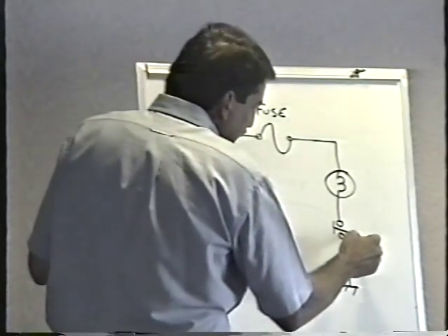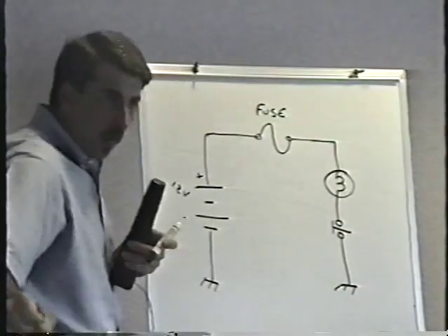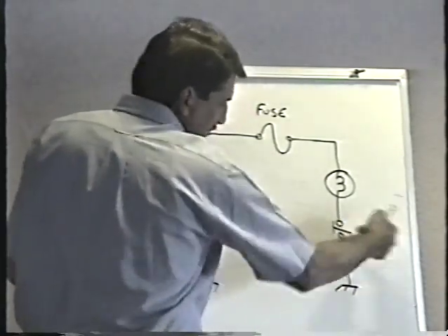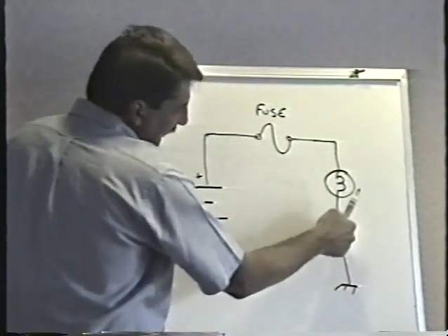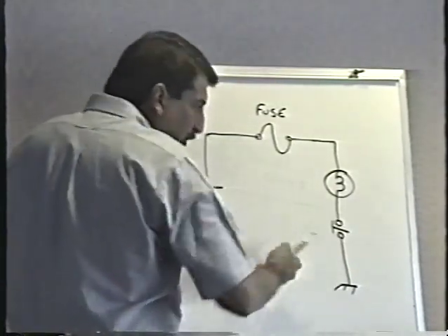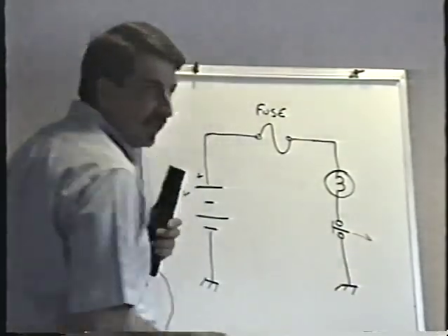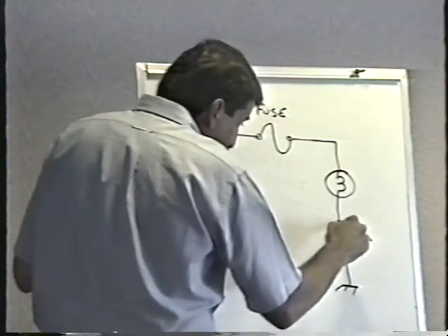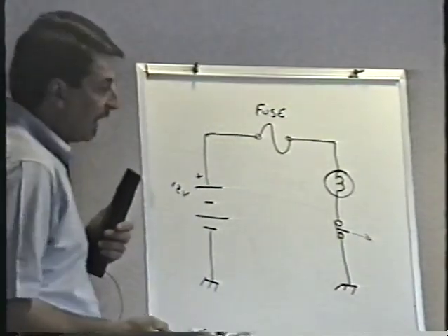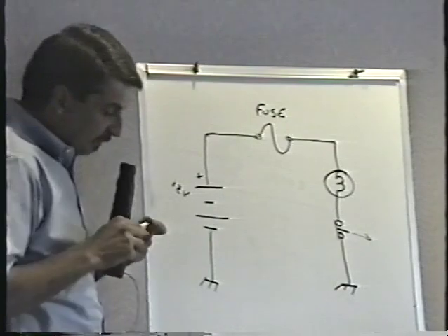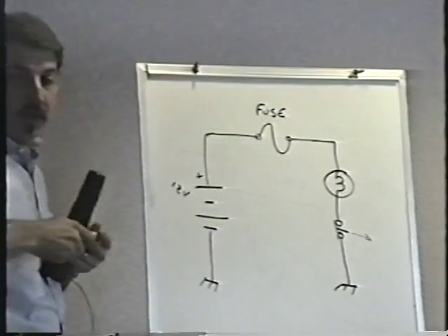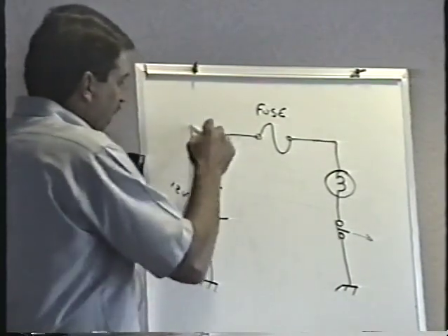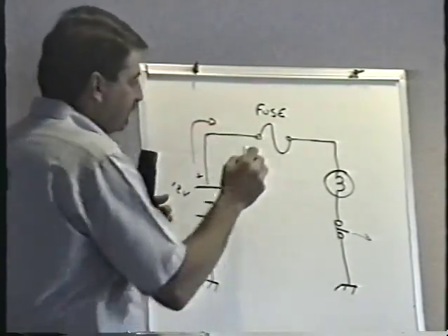Now, this switch, this is the switch that's in the door of the car. When you open the car door, the switch, when the door is closed, this switch is pushed in and it is not making contact there. When you open the car door, the switch retracts, doesn't it? Or goes back to its normal position, really, and that shorts these two contacts together. That completes the circuit, and the electric current, according to conventional current, according to the schematic diagram, the current will flow out the battery like this.